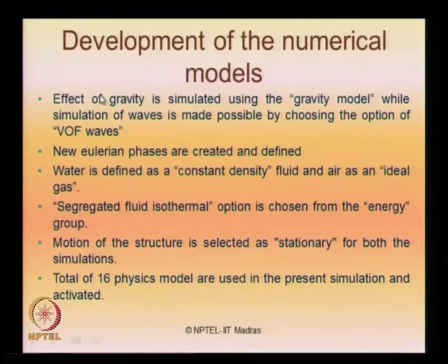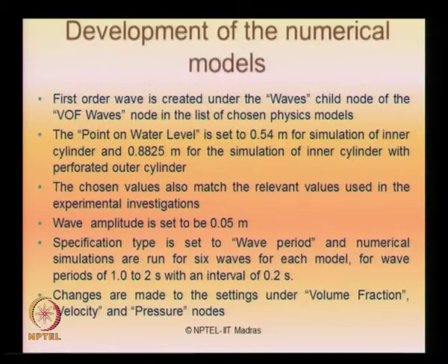The effect of gravity is simulated using the gravity model, while simulation of waves is made possible under the option of VOF waves. The new Eulerian phases are created and defined. Water is defined as constant density fluid and air as an ideal gas. The segregated fluid isothermal option is used for the energy group. Motion of the structure is selected as stationary for both the simulations. Total of 16 physics models are used in the present simulation and then activated subsequently.